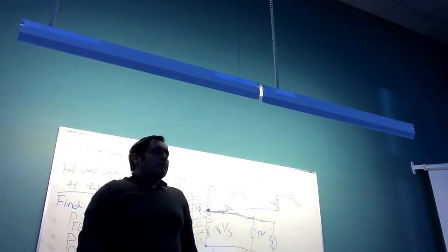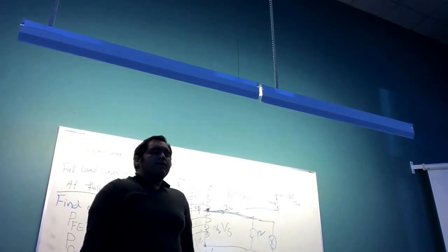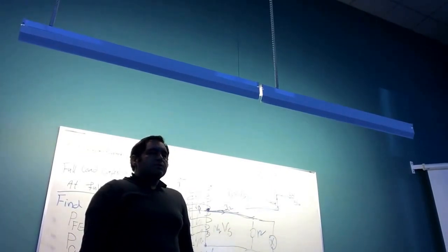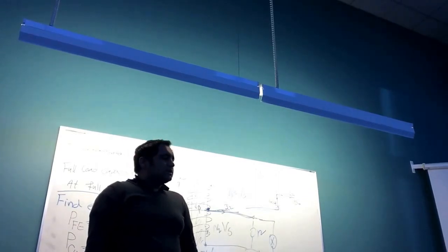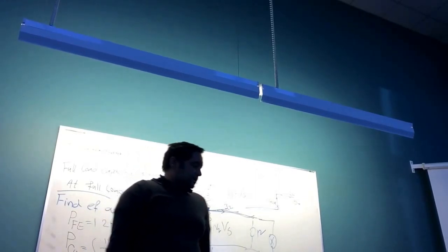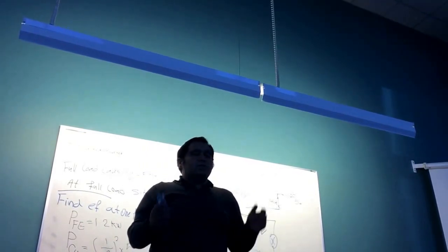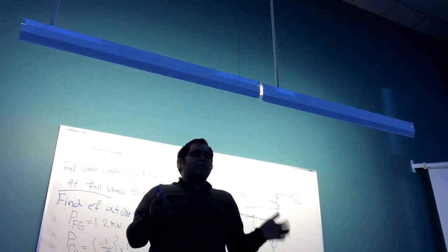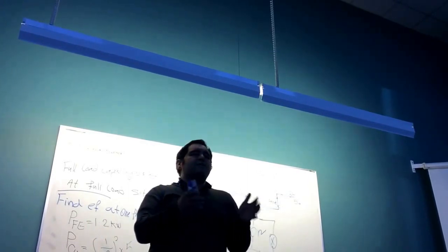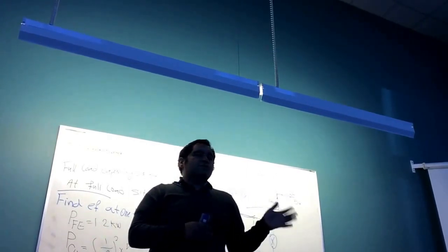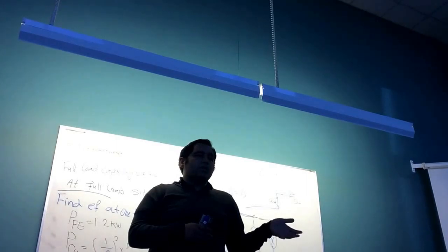So once in a while, you need to go and have a look at your transformer to see if the oil level is okay or not. Also, you need to look at the quality of your oil and see if it is okay. Why? Because after some time your oil quality will be reduced, to a stage where you need to replace your oil. Why?